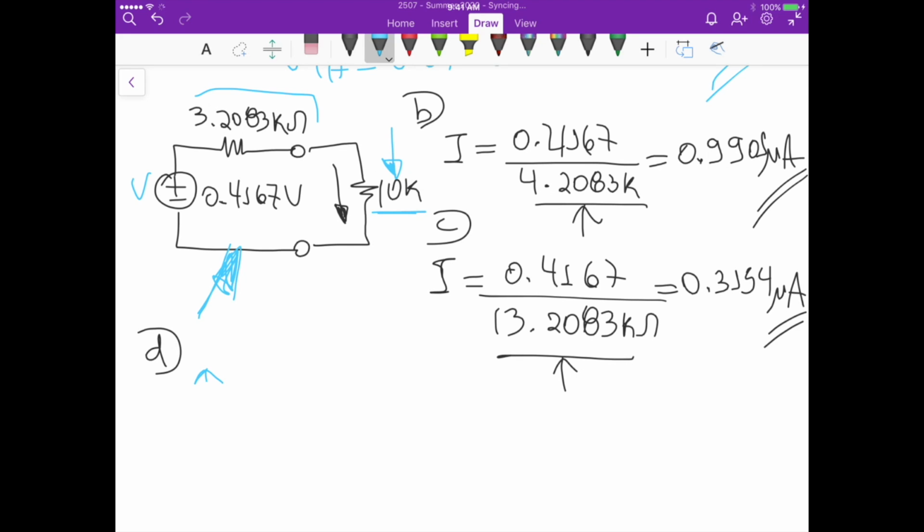If you remember, we would have something that looks like this, right? So this peak here, if this is the resistance and this is power, the maximum power here occurs exactly when our R load is equal to the Thevenin resistance. Okay, so that's also one of the importances of using Thevenin's theorem. Okay, so that's it for this problem.